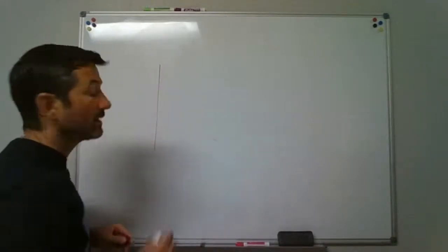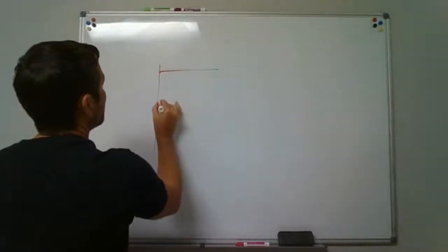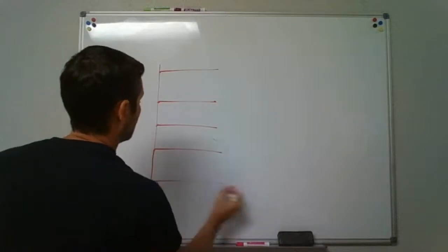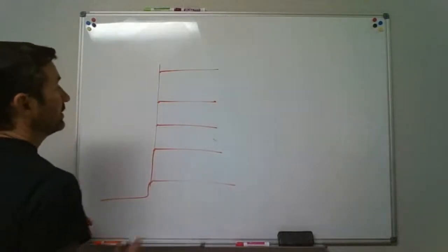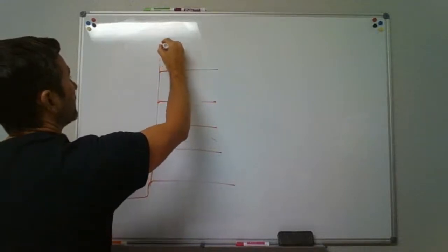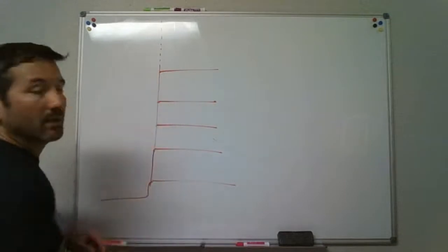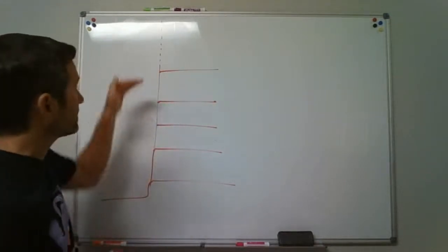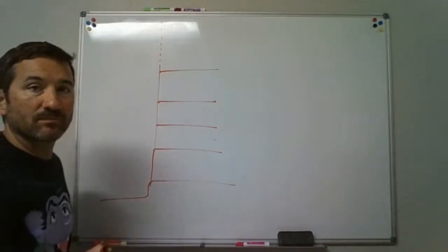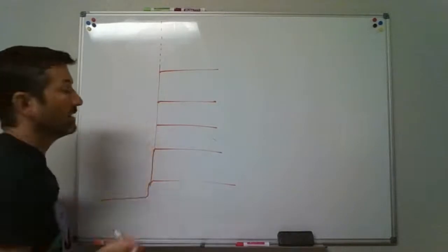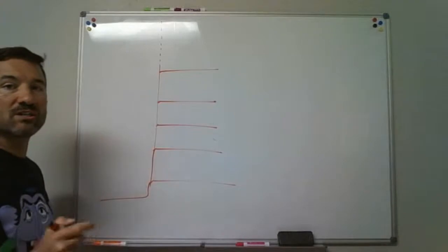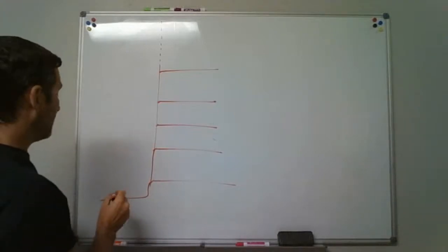Okay, so there you might have a stack that's got drain lines, horizontal branches coming off of it. All right, and then the drain runs out that way. 1, 2, 3, 4, 5 of them. And then above that highest connection that's receiving some drainage coming into it, that is going to be called a stack vent. Okay, stack vent. But now we've got one that's called a vent stack. It's just vent, and we need to put that in.